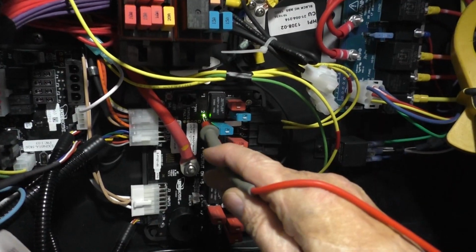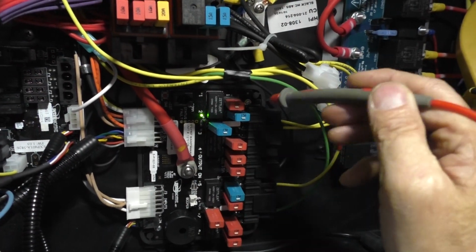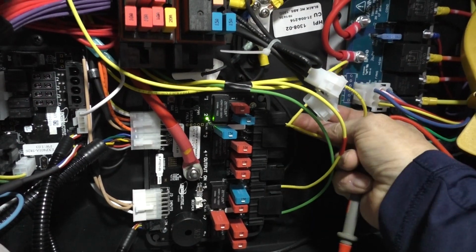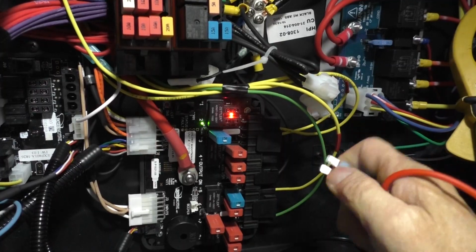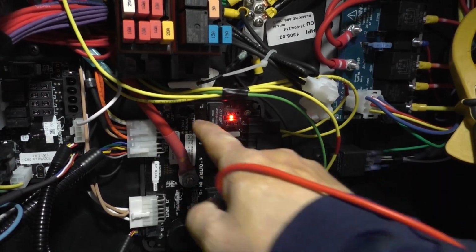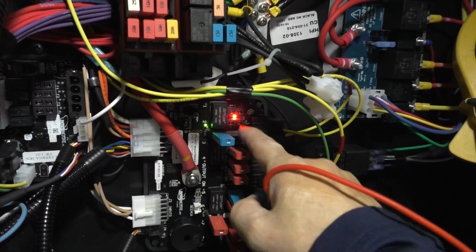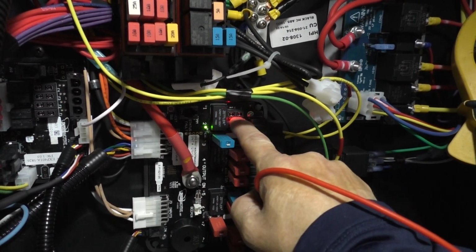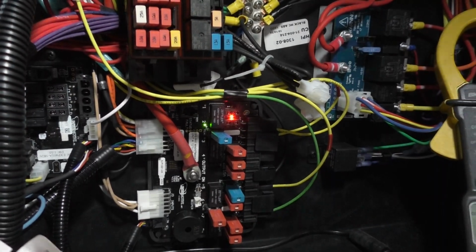When we turn on a load, the green light indicates that there's power at the relay. There's power at the fuse socket, which means there is power on this wire for the high current relay. Now, if we blow the fuse and we've got a short, you'll see the red light turn on. We still have the green light indicating that the relay has power and it's sending power out. The red light means the power is not going across the fuse. This is a quick and easy way to determine the issue.